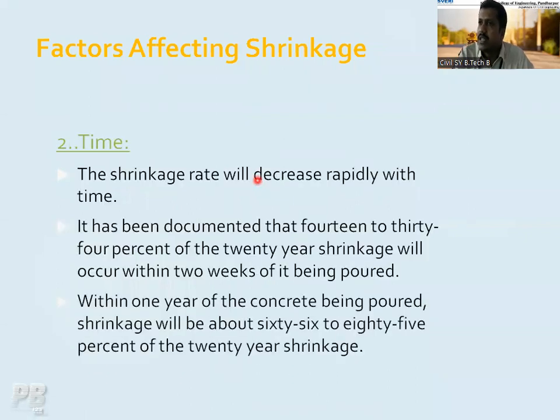So the shrinkage rate will decrease rapidly with time. It is documented that 14 to 34% of the 20 years' shrinkage will occur within 2 weeks of the concrete being placed in the structure.